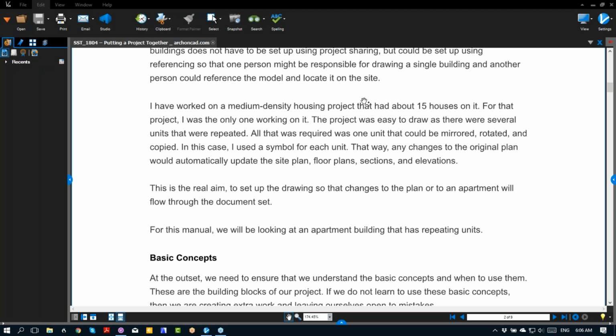If we're building a BIM model and we put a symbol with a multiple unit and we put the walls either side of it and we put another one next to it, in fact, we end up with two walls in the same location. If you put a wall on the left side of your plan, what do you do on the right side of the plan when you get to the last unit? You've got to put a wall in there. So there are some actual challenges if we want to be totally correct with our models and with our modeling, in how we take care of those symbols.